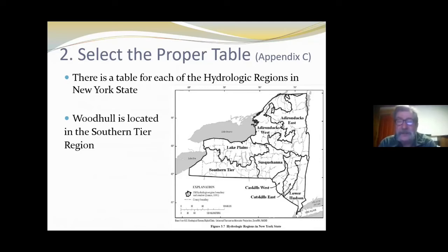Hopefully they're close. Some of the experiences that we've heard are that they might be a little bit too big, but again, nature will start to adjust that channel by moving in new sediment or removing a little bit and placing it in different spots. So you're kind of jump-starting that whole process that nature is constantly involved in every time there's a bankfull flow and that material gets redistributed.